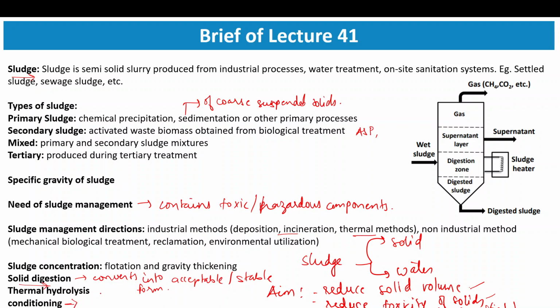Now, if we talk about the characteristics of sludge, sludge usually has some charge, as I mentioned earlier during the initial primary treatment of coagulation and flocculation. Pollutants have some charge, and this charge makes them difficult to come closer, so the solids will not be able to come closer.